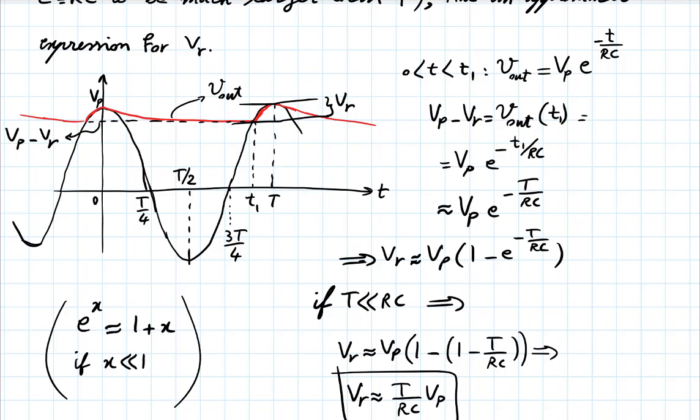That's when you're trying to charge the capacitor, right? At time t equals 0, just before t equals 0, that's when the capacitor was kind of reaching its maximum value, right? And was going to go flat before it realizes that it has to discharge in the resistor, right? But just before that, what's the slope of that curve, the cosine curve, as it reaches its peak? What's the slope? 0. So the capacitor current is reaching 0 at that point, right?